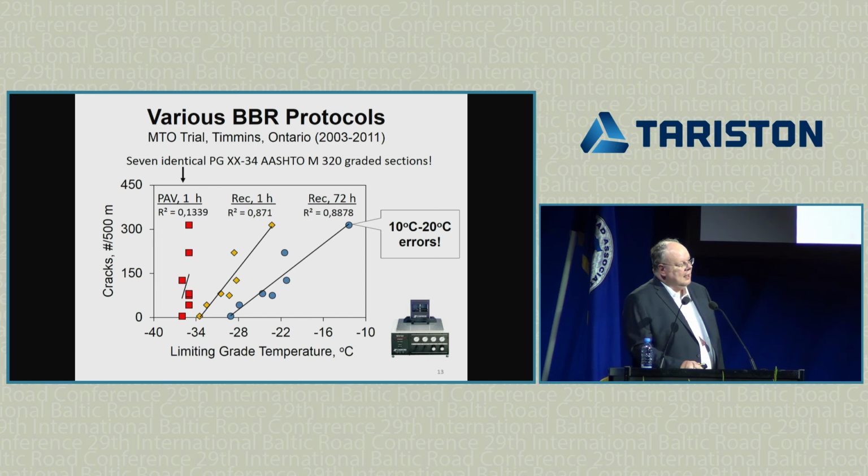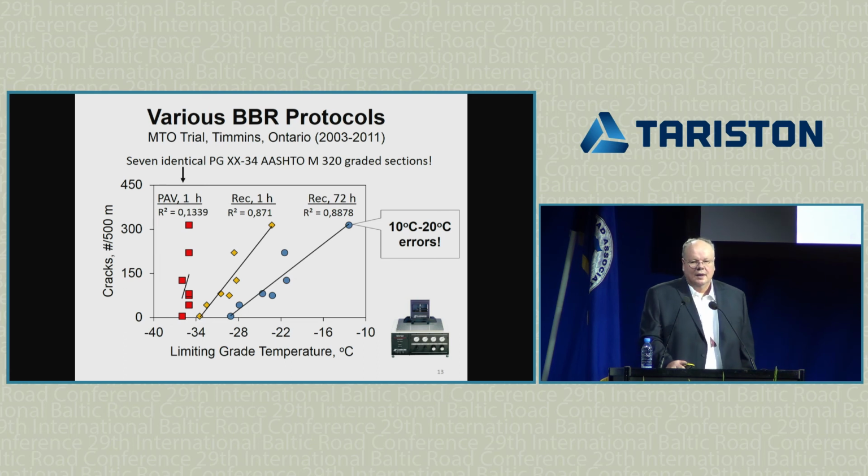The other interesting thing is that this test section here grades perfectly at minus 34 or a bit less, minus 33.5 or so. So at 8 years, the PAV has worked fairly well for that because it was started off as a minus 36 and it's now only a minus 34, no cracking, that's what we want. So for good asphalt cement, SuperPave works fairly well.